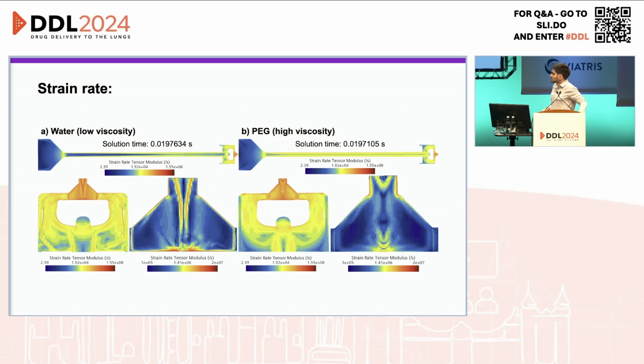And looking at the shear rates at the swirl chamber, actually, we get some very good looking data. So we can see that at the air core, we're getting these strips of very high shear rates at the liquid air interface. And what that shows us is that we are getting the energy required for that breakup of the fluid bulk to finer droplets.